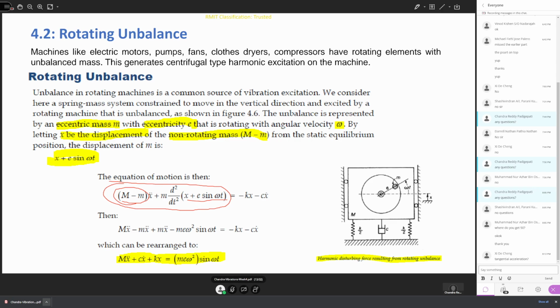And in the free body diagram here, you have the spring force, so k by 2 you can add up. So the spring force is k into x, and the force due to the damper is c into v. These two forces are equal and opposite, so the spring force and the damping force will go with a negative sign. All right, so now we can